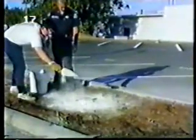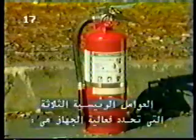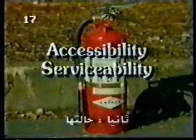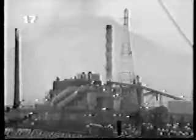Check its serviceability by first checking the inspection tag and noting the date of the last inspection, maintenance, or recharging. Examine the lock pins and tamper seals to see if it has been actuated or tampered with, or if there is any physical damage to its operation. Check the discharge nozzle or horn for obstructions, cracks, or dirt accumulation. Determine if it is pressurized. If an extinguisher is found to be deficient by more than 10%, it should be removed from service and replaced.